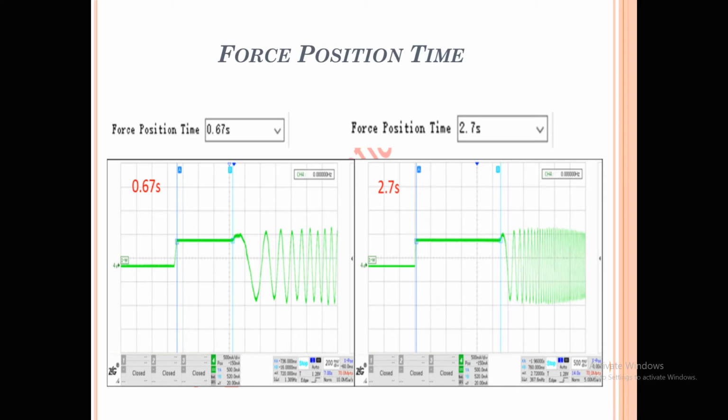If you select a higher value, it will also slow the operation, but it will provide you a smooth startup. Usually in a ceiling fan application, we always try to go with the PSD setting, so this particular setting is useless for us. Just leave it at whatever default value comes with the different manufacturer ICs. That's not an issue for you for a ceiling fan application. If you're going for other applications, then you have to select these values.